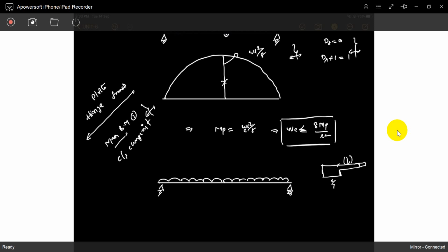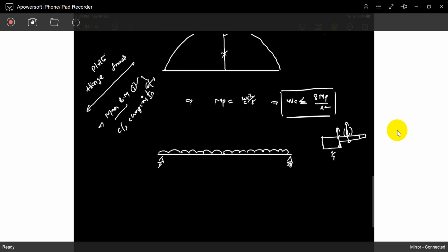It is the maximum bending moment applying, but maybe chances are there when the cross section is changing. Okay, we have to check it. Later we will see. So just remember first: a plastic hinge is formed at the maximum bending moment location, and at cross section changing locations also. We'll see later. Okay, we will do problems.